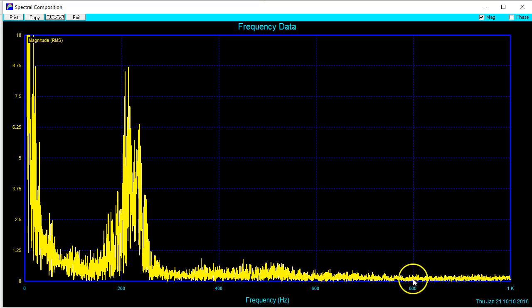But there may be something going on at 900 hertz or 700 hertz or 600 hertz, or oh, now we're starting to see some significant noise down around 550 maybe. There's something going on there that if you didn't sample it, it would create aliasing artifacts down here that would affect your flight. Okay?